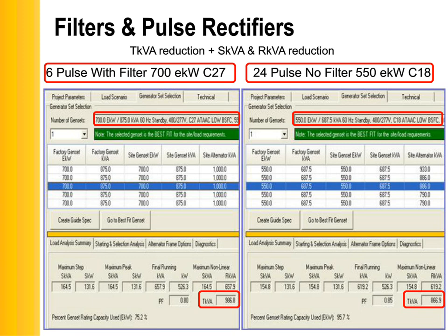Remember I said the higher your pulse rectifier, the more linear you are, the less harmonics and distortion you have. Now we're able to reduce the genset to a 550 kW C18. So we started with a 750 kW C27. Now, this is just one UPS load. It was a big UPS load, but we're able to reduce the genset pretty significantly, not just a rating, but a model.